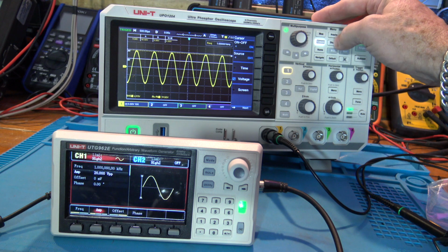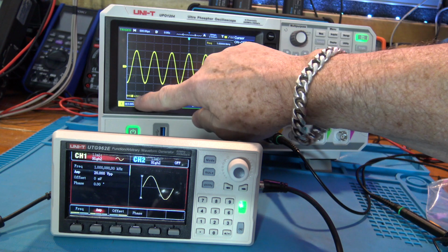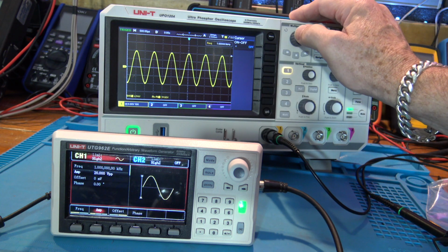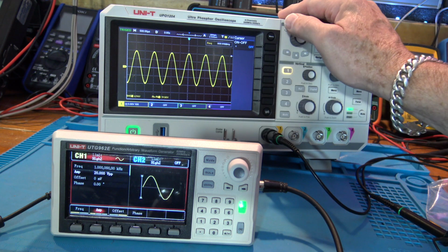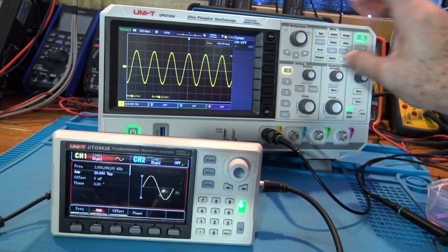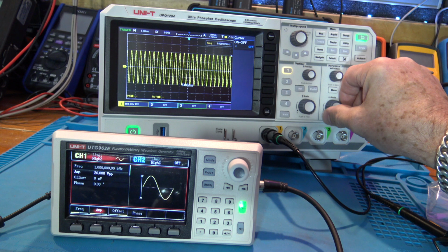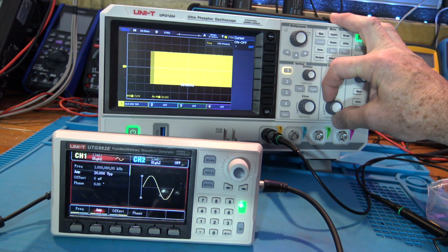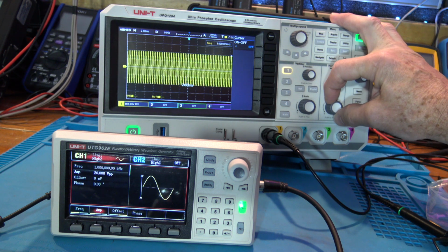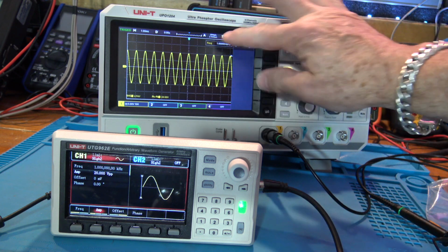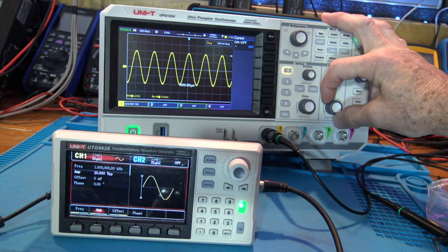So there's my screen. I'll turn off the cursors. 6.94 volts, 20 volts peak to peak. It was kind of bouncing around between 19.8 and 20 volts. Let me get more waveforms to see if it really is okay, there's 20 volts. It kind of bounces between 19.8 and 20 volts. So you have to get more waveforms sometimes to get a better math readout, so the scope has enough cycles to get the math.